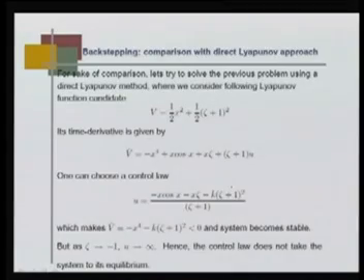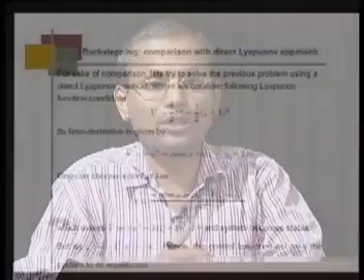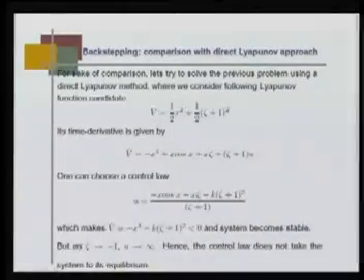So, what we essentially did here in backstepping control is that first we simplified the stabilization problem by stabilizing the first subsystem, and then I augmented the Lyapunov function to define the global stability of the entire system. Now, instead of doing that, if I would have directly selected a Lyapunov function like this and then taken the Lyapunov derivative, let us take the comparison.